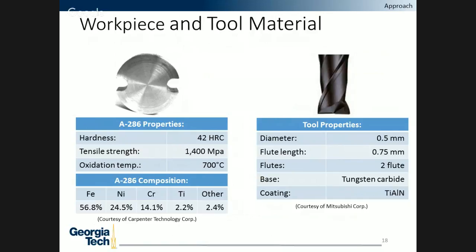To go more into the tool, we'll be using a 0.5 millimeter diameter tool that is smaller, that's on scale with the leaded mechanical pencils, and it will be a tungsten carbide tool with a titanium aluminum nitride coating. And just to give an example, feel free to open this bag and use a magnifying lens to take a look at the tools.